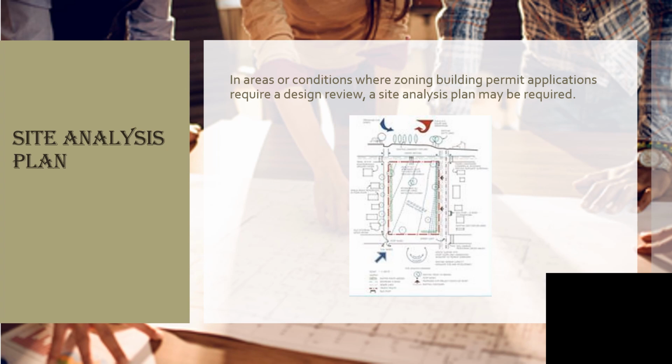Site analysis plan. In areas or conditions where zoning and building permit applications require a design review, a site analysis plan may be required. The site analysis provides the basis for the proper design relationship of the proposed development to the site and to adjacent properties. A site analysis plan typically includes the following: a vicinity map showing the location of the property in relation to adjacent properties, roads, and utilities.